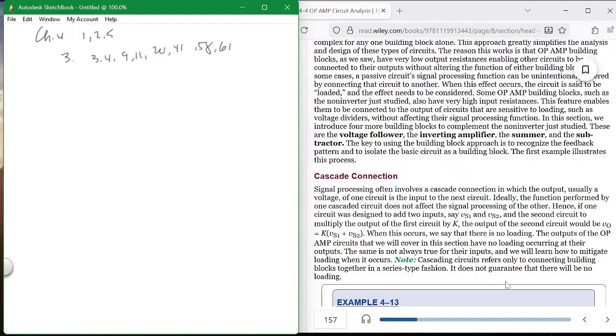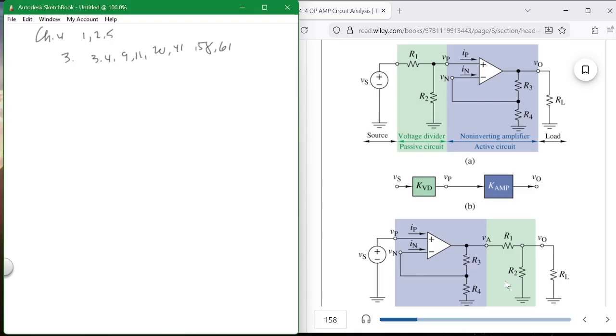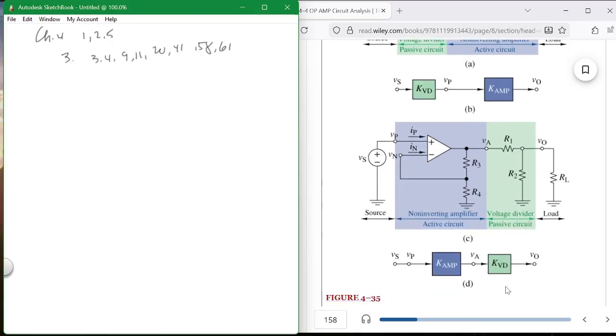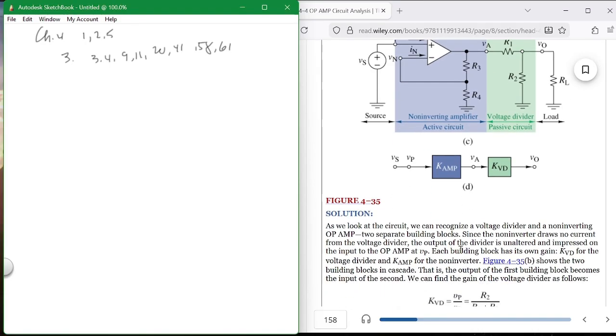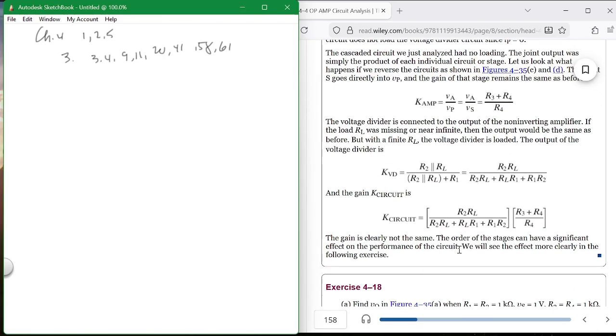So what are op amps really good for? A lot of things. You can do a lot of circuits with them. As a matter of fact, when I first started teaching, they actually had, and they still may have in some places, an analog computer. What are analog computers? A bunch of op amps with various things attached to the front end of them. So you can put a capacitor in front of them, you can get an integral. You can put a derivative. You can put an inductor and get it. You can put capacitors in and get derivatives, integrals. You can do all kinds of stuff with them. You can do all kinds of formula analysis with them.